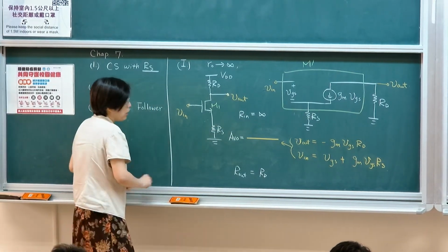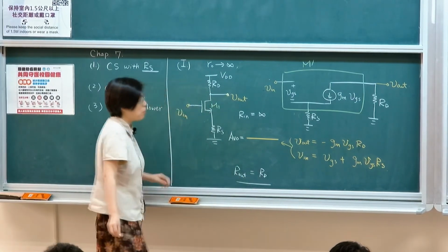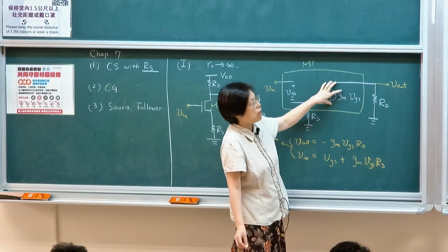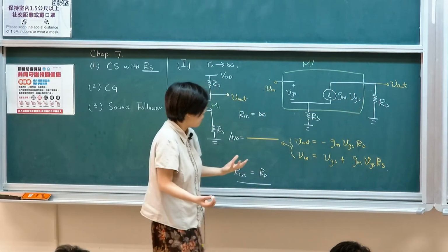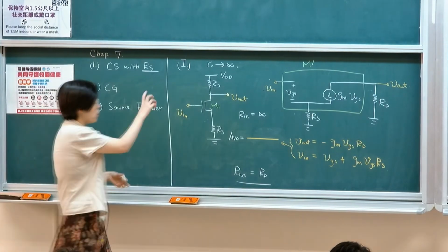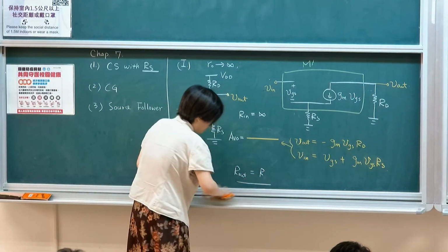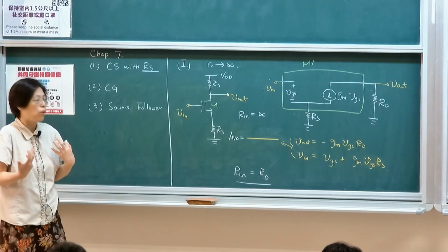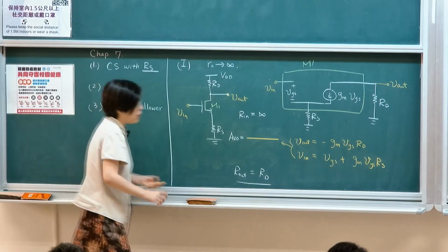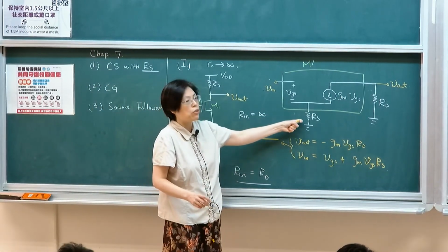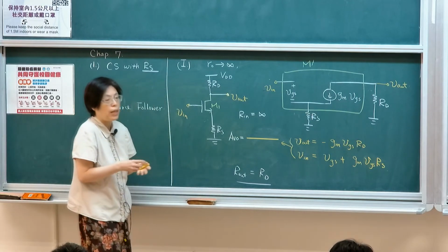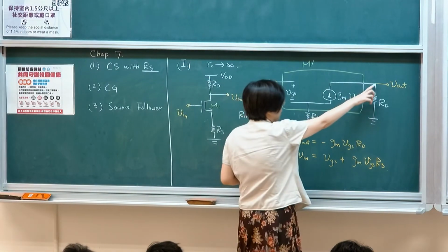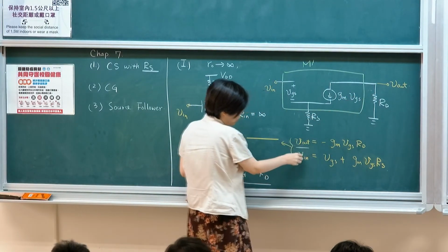Then we look at output resistance. As we already discussed before, because we're ignoring the effect of R_O, you're assuming this is an ideal current source. Therefore, you only see R_D, the effect of whatever is externally added as your loading resistor. And lastly, if you want to analyze the overall voltage gain, once we insert R_S, the gain will attenuate a little bit. The way to do this is to find the output voltage in relation to the input voltage.